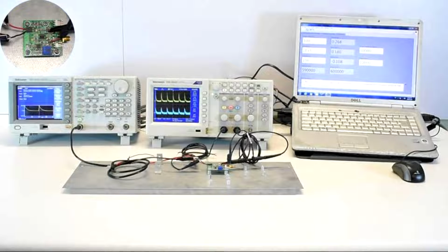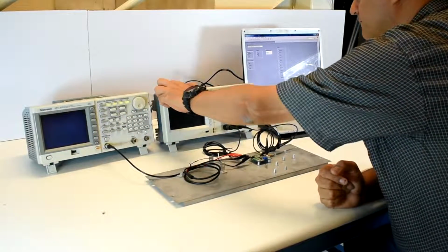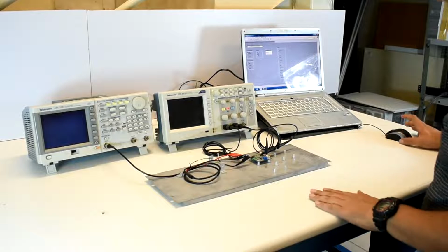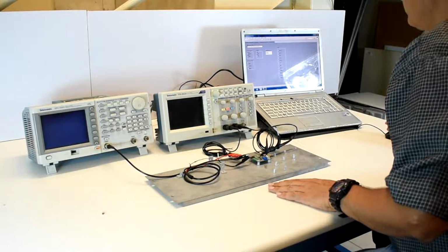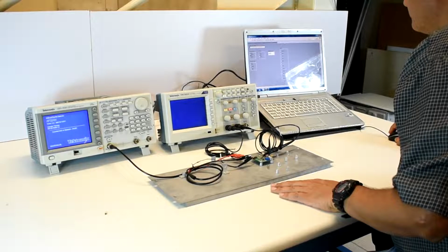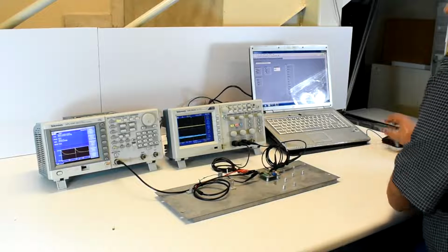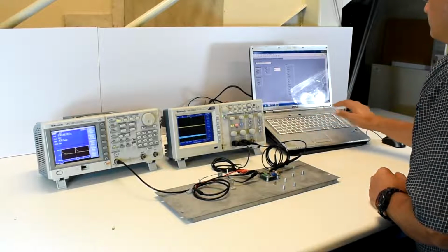In this picture, we show the attenuation factor and phase shift versus frequency measurement experimental setup. The process of measurement is as follows. Turn on the Tektronix function generator, Tektronix oscilloscope, and PC host with LabVIEW. Verify the correct input and output connections of the feeding and reading out electronic board.